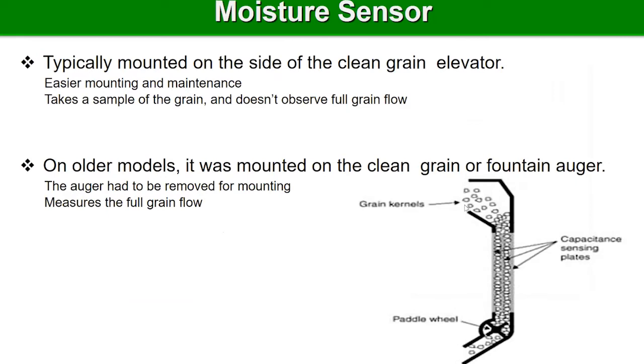And one important thing here is the moisture sensor. Think about it. We harvest 200 bushels per acre, meaning the yield monitor is showing 200 bushels per acre at 20% moisture content. And in another field, we are harvesting 160 bushels per acre, but at 15% moisture content. Which one is higher, and how can we adjust this?